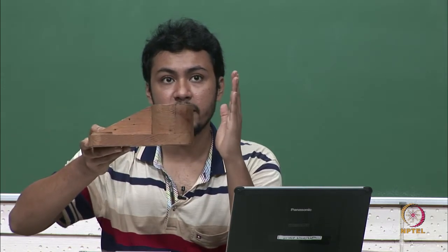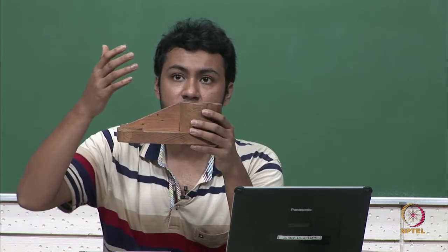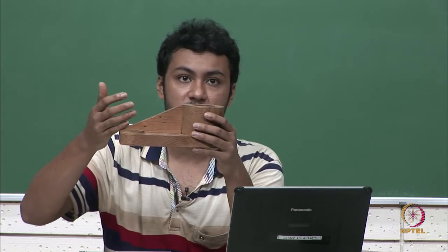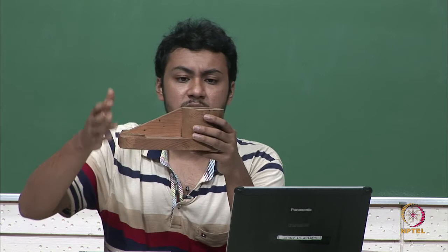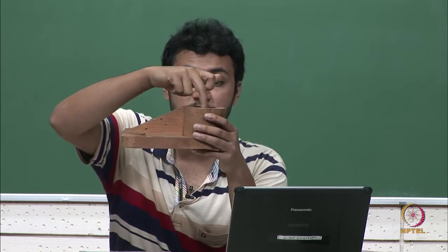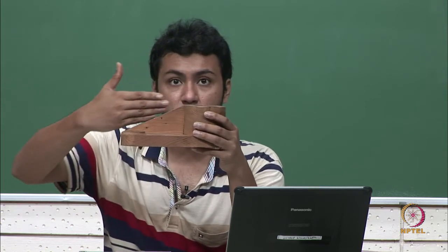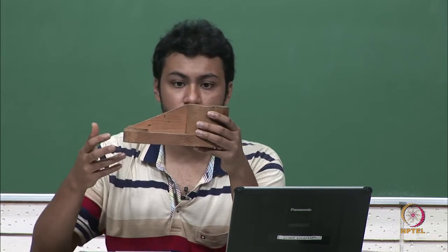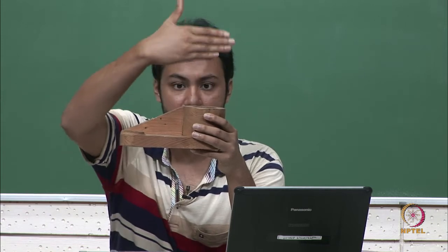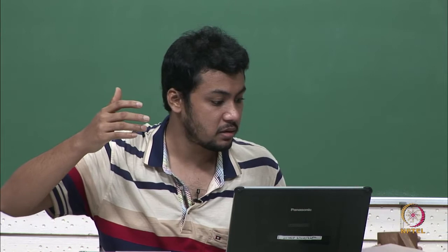The section rule is actually, after sectioning you should be able to understand most of the features, what are the internal features in most cases. So, this time we have chosen this cutting plane, so that we know what is the internal feature of this area, and after cutting what we will be looking at, that I will just show you, but first I will draw the cutting plane. The cutting plane is this vertical plane that I have to show in the top view, I have to represent that.